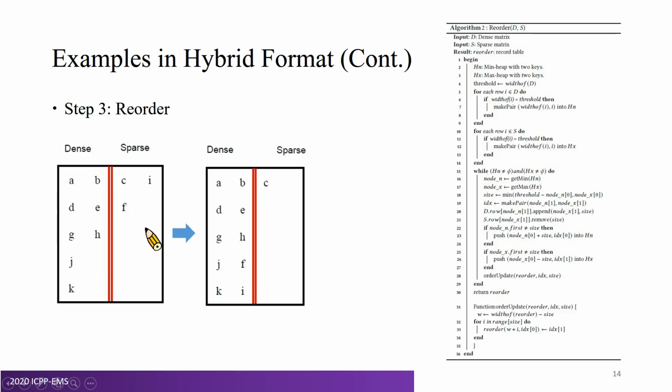So we redistribute the data position, move the elements from the sparse block to replace zeros, and reduce overall computing costs. In the process, since the position of the selected elements has been changed, a record table will be updated to fix the final calculation result.